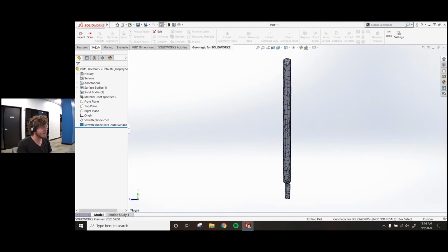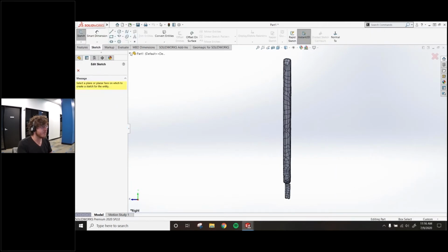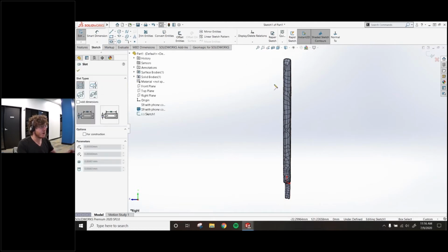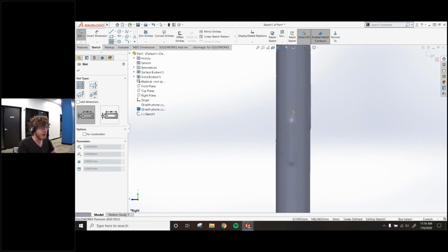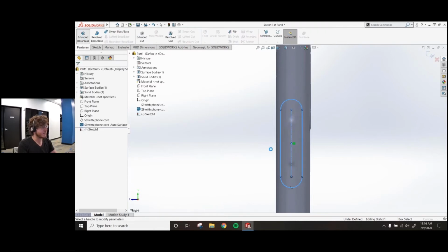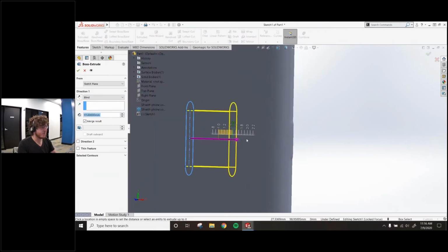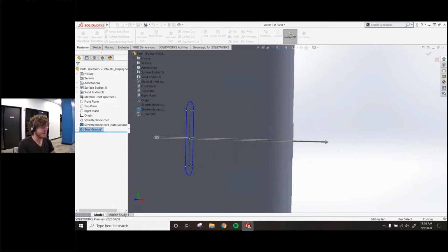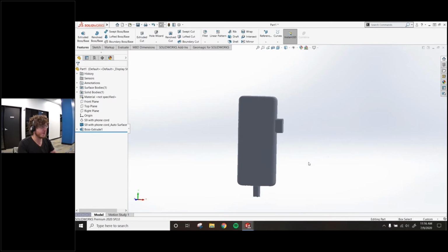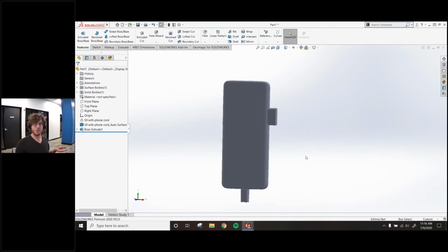So as we're all very familiar with, I can just go right into the sketching tools and treat this like a solid body. So I can go in here, maybe I want to outline some of my button locations. I'm holding down Control right now so I don't snap to any of those points. But here we go. Sketch right in here and then extrude this out. And if I merge them together, it creates a single solid body. And now we're just building up our reference body.